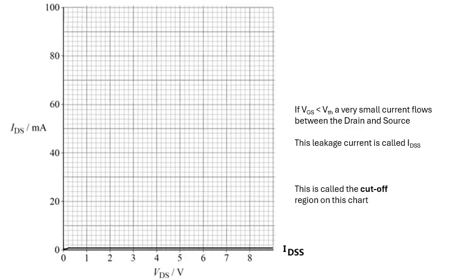Looking at this graph, this graph is VDS, your drain source voltage, against IDS, the current flowing through the transistor. Now, if VGS, the gate source voltage, is less than the threshold, as I said, a tiny current will flow, 25 microamps, tiny, ignore it, it's not really important.